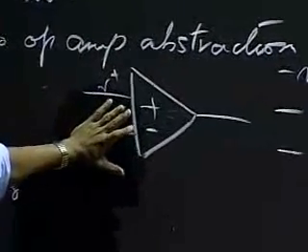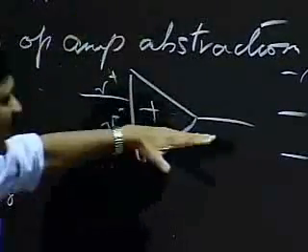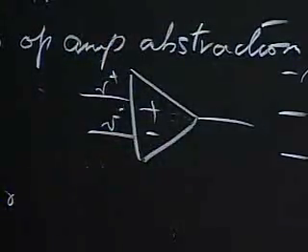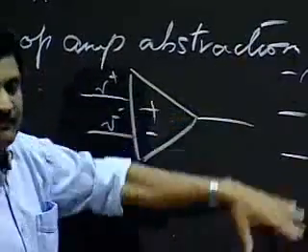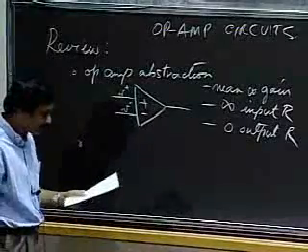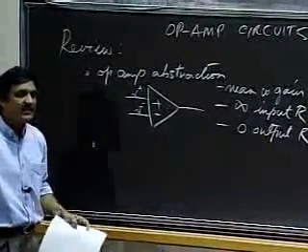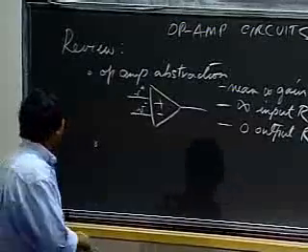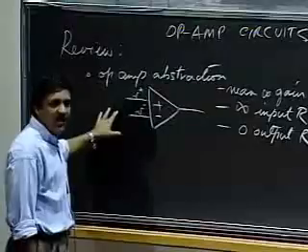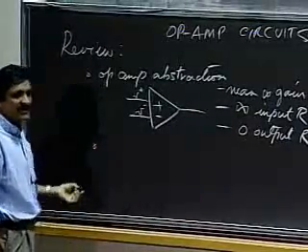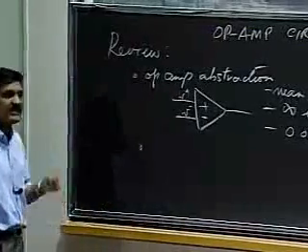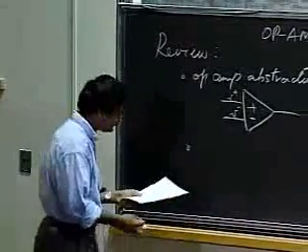To some extent, you have to think about that with the op-amp too, because if the output hits the positive rail or negative rail, it isn't going to behave like you expect it to. But fundamentally, with this ideal model, it becomes really simple to build circuits with the op-amp. So therefore, it's become a key building block for circuits. When circuit designers build analog circuits, very often their primitive building blocks are an op-amp, resistors, capacitors, and some of our other primitive building elements.